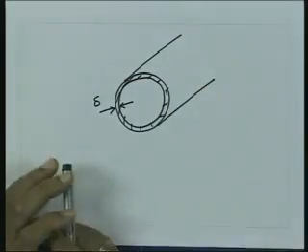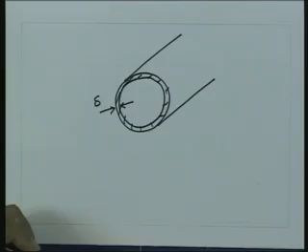That is the reason that in microwave components, where the frequency is very high and the skin depth becomes only a micron or so, the surface has to be extremely good and perfect, because any small perturbation on that surface, where most of the energy is confined, will affect the propagation of the electromagnetic wave.